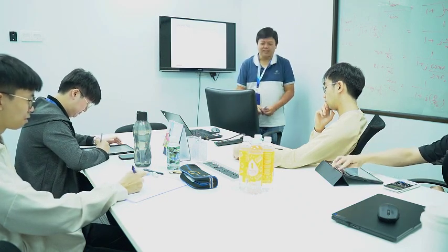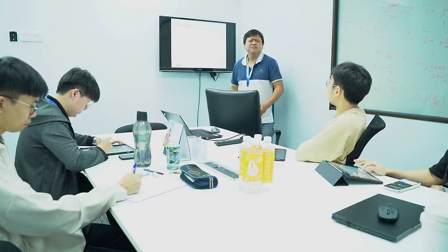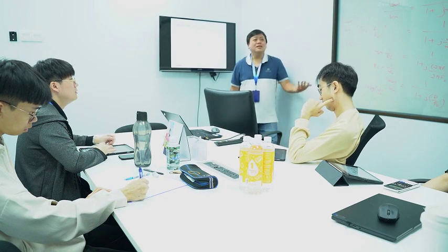Interesting, right? Because you learn this way, you make your learning more meaningful. Sometimes you just take minus 3, and if you don't know the theory behind that, you don't feel the learning is interesting. Now you know where the minus 3 dB comes from. It comes from a simple equation. If you manipulate a bit, you can get the minus 3 dB. So you see, from a simple RC, you can learn so many things.